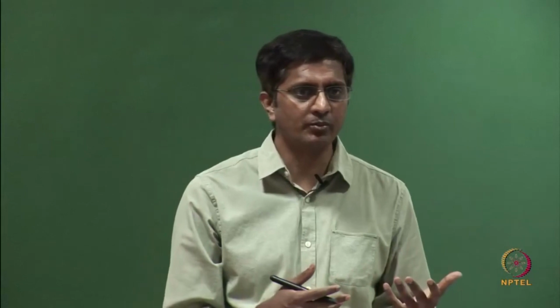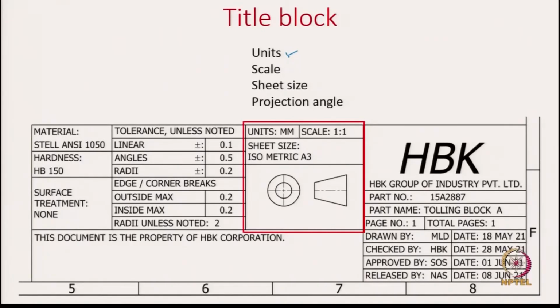You may use millimeters or inches depending on the location you are working in. For example, Europe probably uses different units, and North America might be using different units. Since now we are in the global market where the design originates at one company, the fabrication happens in another country and the sales happen in another country, to make sure the communication is flawless, this information needs to be captured, so that there is no misinterpretation. You need to mention which units your dimensions are in, and the scale.